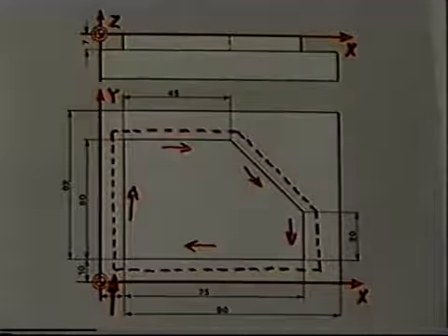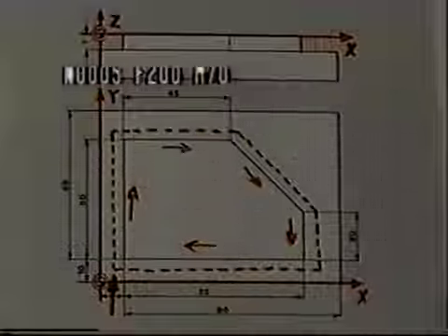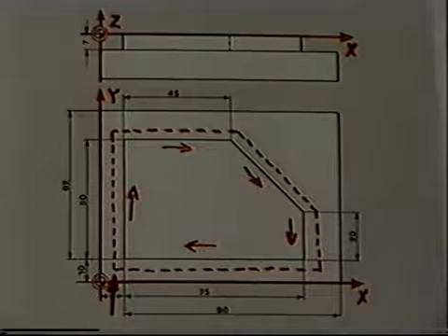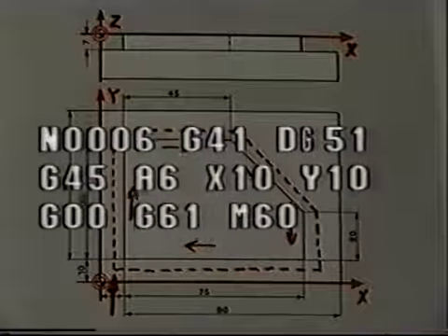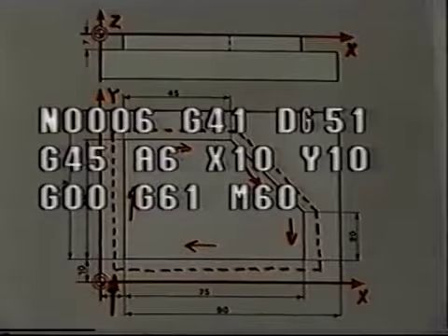Well, let me program the thing. Move over the workpiece. First the feed rate, spindle speed, etc. Now contour compensation starts. My tool is in the cutting direction to the left of the contour. The command was G41. Then I enter the compensation number. Now I've got to program how to travel to the contour. Here's a straight line. I'll simply move in parallel with the contour.